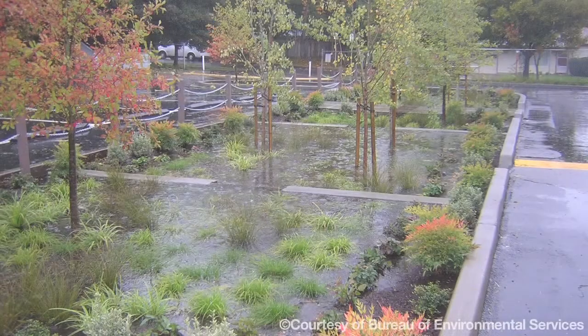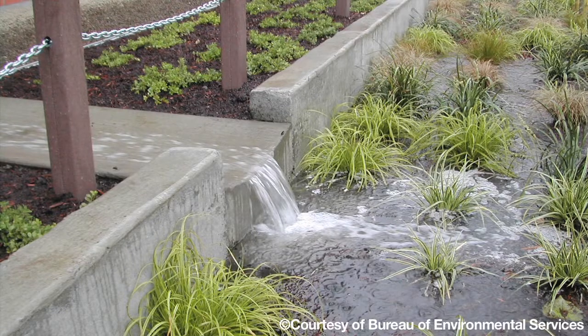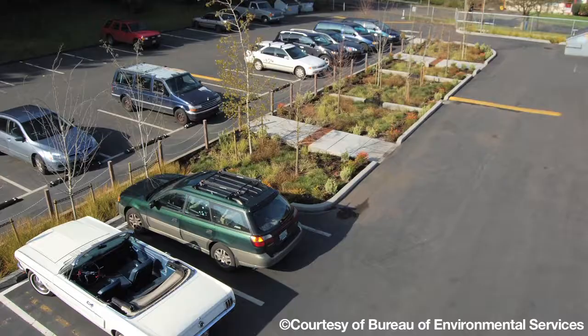An alternative to replacing the sewer lines was to retrofit the school with stormwater infiltration facilities. The design team planned a number of stormwater solutions around the perimeter of the building. The project included a rain garden, a vegetated swale, 6 smaller infiltration planters, and 3 dry wells. The facilities together manage runoff from approximately 2 acres of roof, playground, parking lot, and street surface.